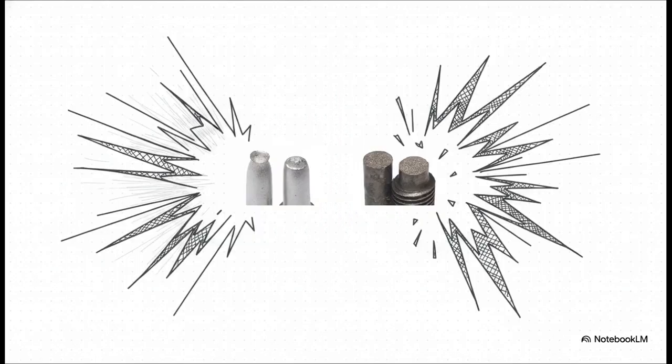You can literally see this difference physically when you look at test specimens. Check out that classic drawn-out cup and cone surface on the left. That's your textbook hallmark of a moderately ductile break. The metal was basically desperately holding on, stretching out before finally letting go. And here's a neat detail. That cup and cone failure actually happens at a 45-degree angle to the tensile axis because it's driven by the maximum shear stress. Now compare that to the flat, granular, almost perfectly sheared face of the completely brittle fracture on the right. Night and day, right?